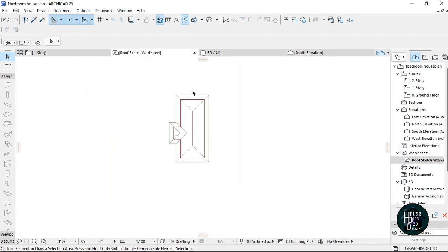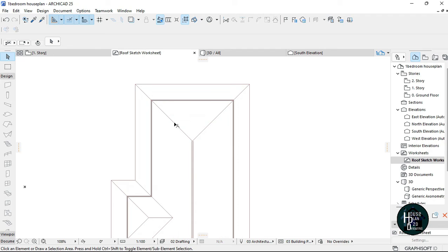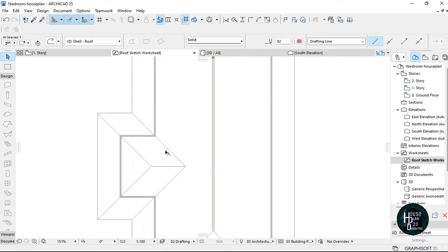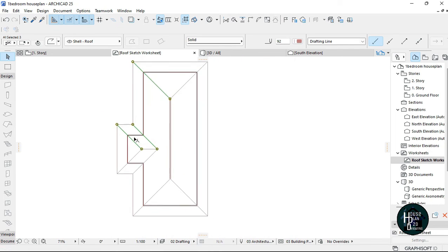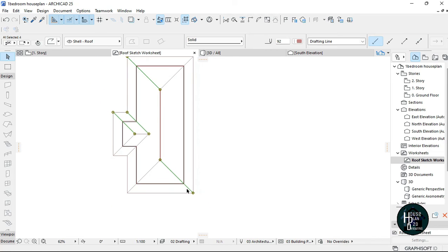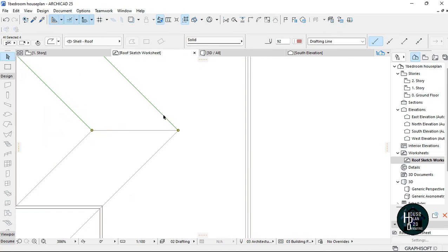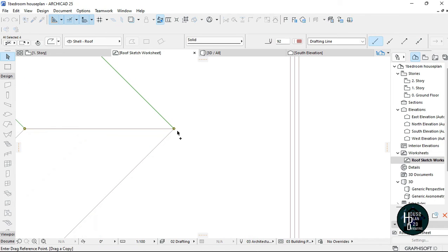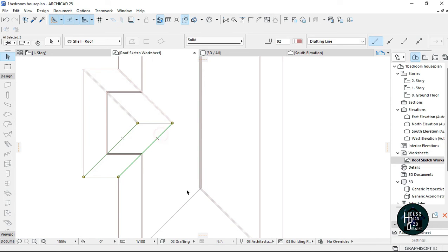Now, to make this easy for you, this particular line that is bent like this, just click on it, click on this one too that looks like it, and this other side too. Then you just copy. That's what I did here. Ctrl Shift D, move here by copy by 50. Ctrl Shift D, go back by 100. You want to do this for this other side too.